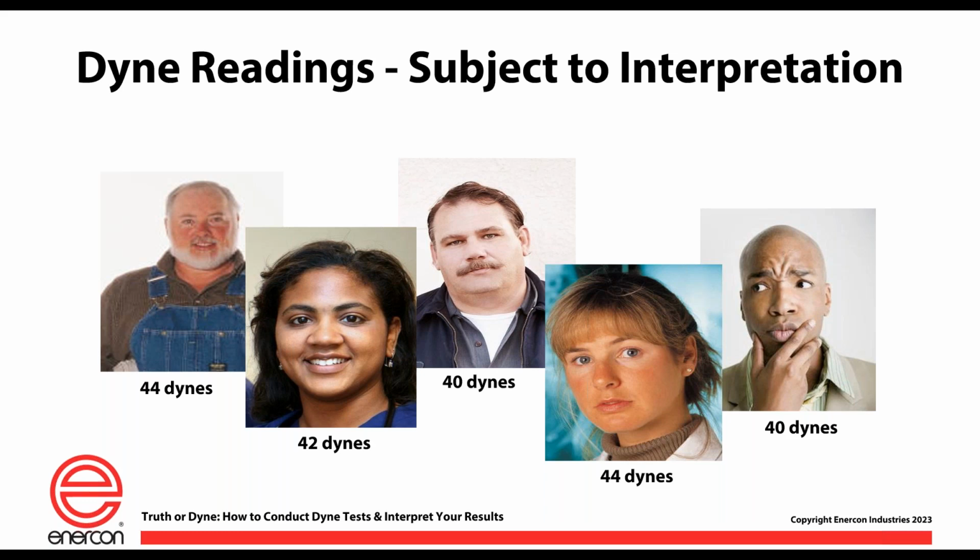If you were to redesign a test method, you probably would design it differently than the method we use today. But furthermore, if you look at the screen now, you see the Dyne values are like 5% difference, or 10% difference. I'm going to tell you right now, there is no way, using a Dyne pen or practically any of these methods, that you're going to consistently and repeatedly determine that tight of a Dyne difference, number one.